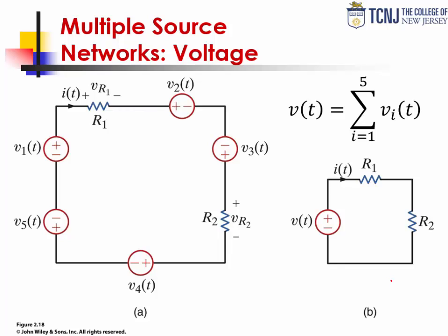What we did with resistors also works. Kirchhoff's laws also work for sources, specifically for voltage sources. When we connect them in series, we can apply Kirchhoff's voltage law to find out the equivalent total voltage of all those sources. Again, we use the algebraic sum of the voltages by using the sign that we first encounter in the direction of the current.